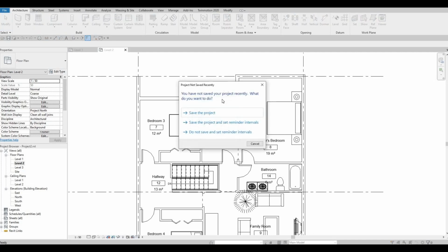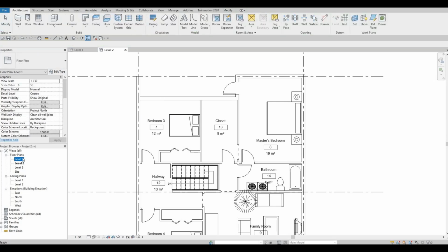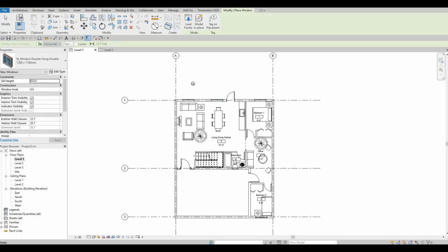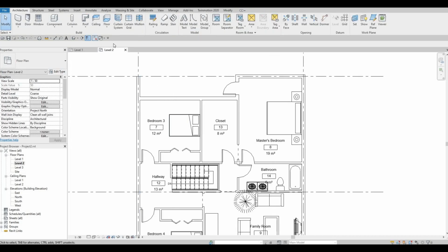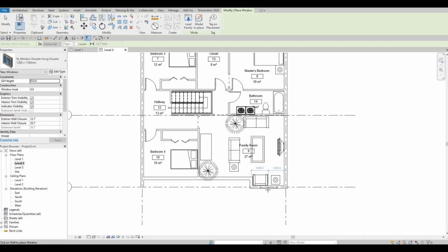So we're gonna add the window that we added in the first floor. So let's go back to first floor and then let's check out what we added. So this will be the window. So I'm gonna click CS and then we're gonna add the same wall or window. So I'm gonna add this window right here and then let's add it here. And then this as well.